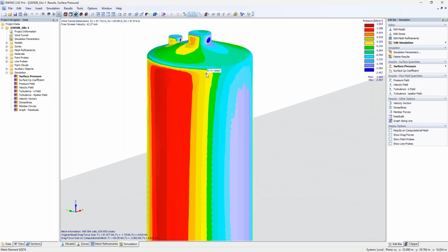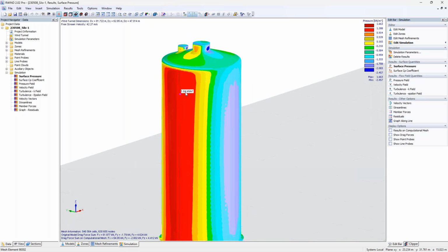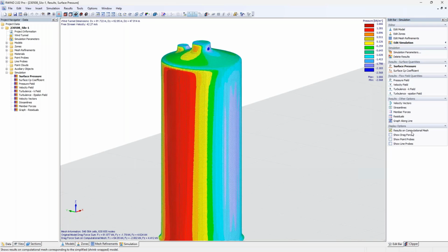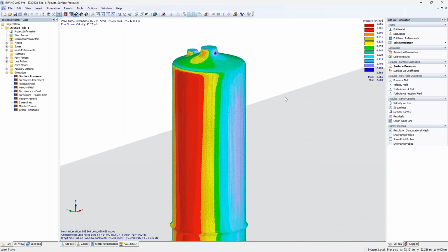Of course, since my structure is closed, we do not have any inner pressure, but we do have a front and a back. This changes once we go into our computational mesh, because this is then a mesh creating triangles surrounding our original mesh in order to have triangles for the CFD analysis, which we need. And they do have, of course, now also a front and a back. But mainly you will only have one value now because we have a certain thickness now. Maybe you can see it later on if I show you some forces.